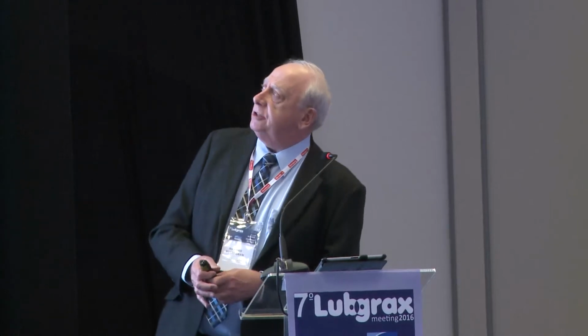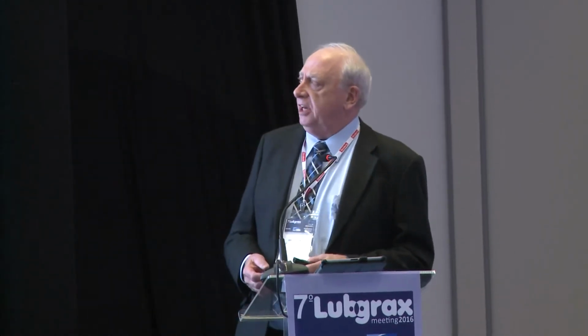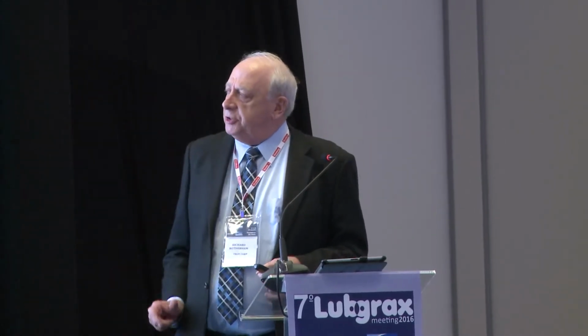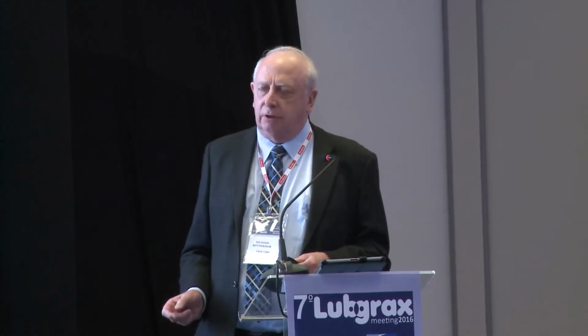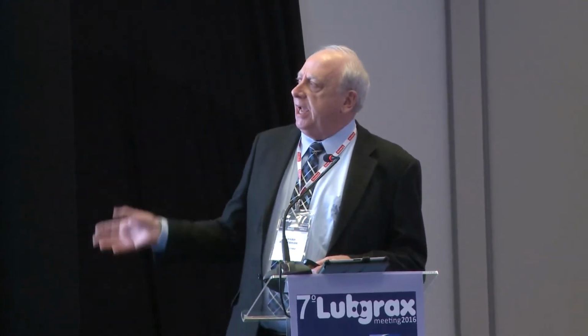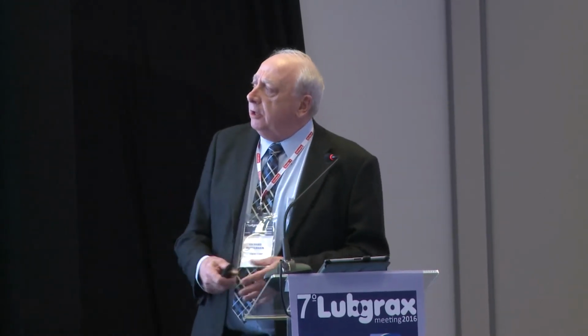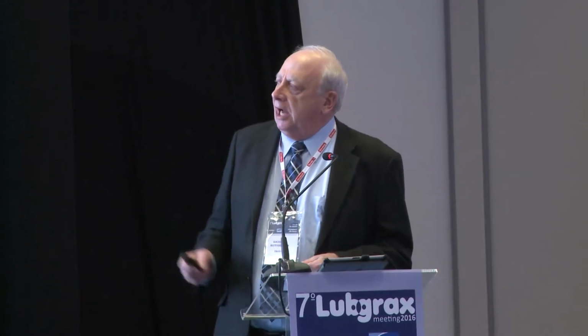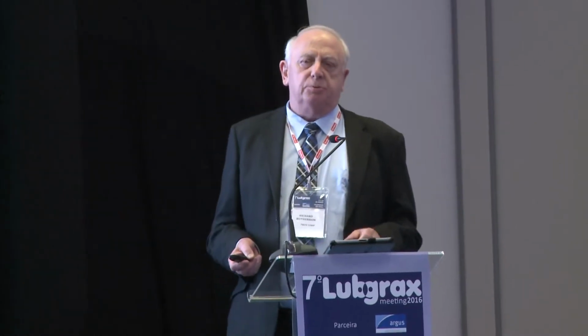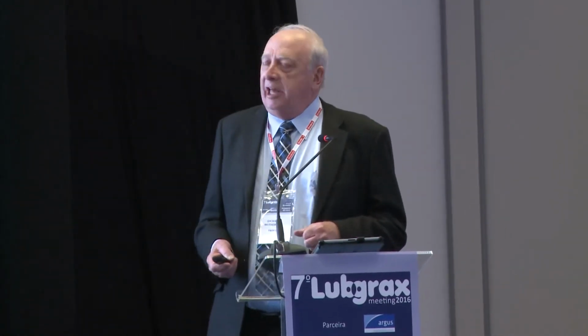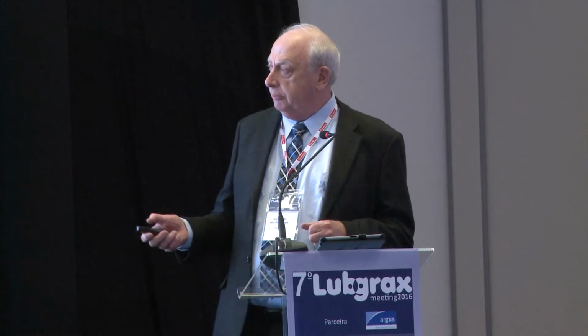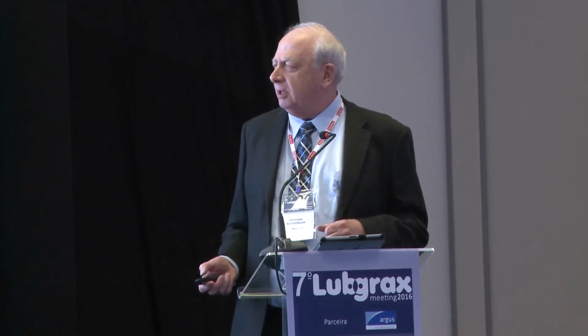If we look at the effects of microbial attack, some are fairly obvious. If a machine or system is out of control and you shut it down over the weekend, you can get hydrogen sulfide odors. Quite nasty. You can get musty odors, and you may even get ammonia coming off systems from attack of things like MEA, monoethanolamine, and other amines.